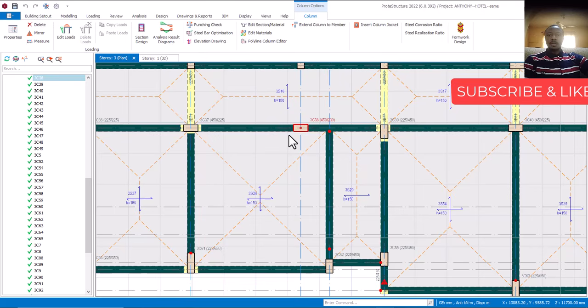So this is how you go about your column, and this is the kind of thing that you can ignore when it comes to column. Some of you might not know. You might have been seeing that and ignoring it. That's fine, but you can now know that the only reason why you ignore it is because those things I mentioned are in place: no warning, your reinforcement was given, utilization ratio was less than 1, and also your ND is okay. Even though that place is showing you an exclamation mark, that can be ignored.